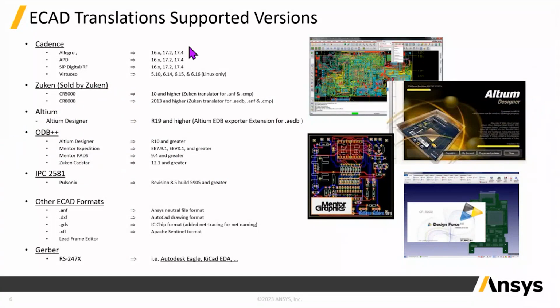Coming to PCB, normally Ansys is not there in any of the PCB design applications or tools. We took a neutral step here. So you design your PCB in any of these tools which are commonly used in industry. We are ready to accept this PCB directly into the Ansys tool. So whether it is Cadence, Zuken, Altium, ODB++, or IPC-2581, you can easily import it and run all kinds of analysis.